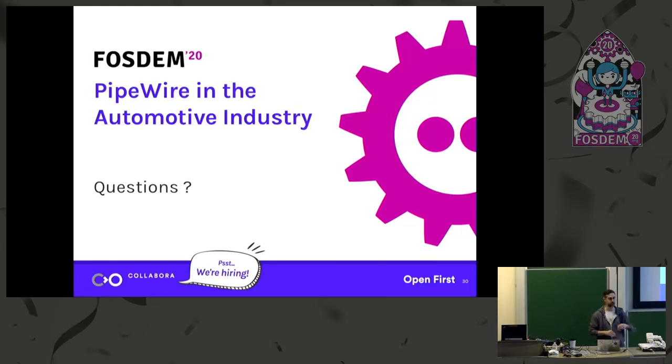In terms of flexibility, you said you were looking to do more flexibility. Were you talking about boot time flexibility or runtime flexibility? Because with the adoption of things like A2B in the audio space now, you're getting nodes that are coming on and off the buses all the time that are making audio harder to manage. Yeah, PipeWire is very dynamic in how it manages hardware, so it can detect things coming up and moving out all the time.